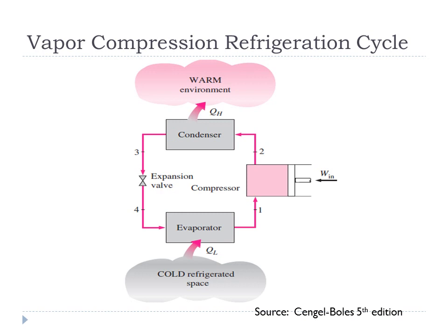With the help of work input, the refrigerant is compressed up to state 2. So 1 to 2 it is compression process and carried out isentropically. Isentropically means reversible adiabatic process, where the refrigerant does not exchange any heat with its surrounding.